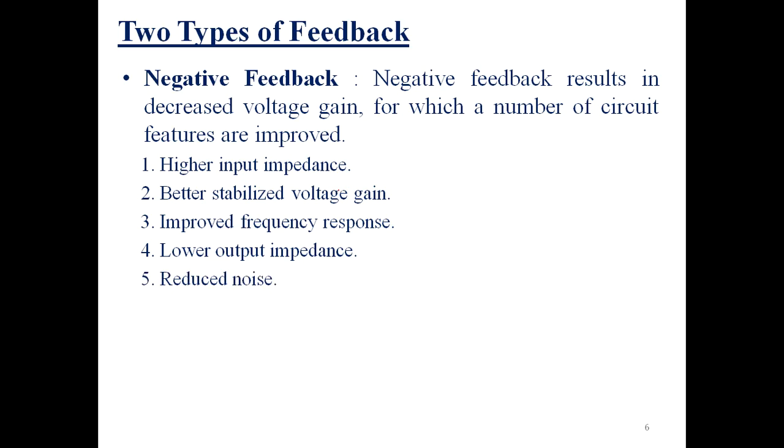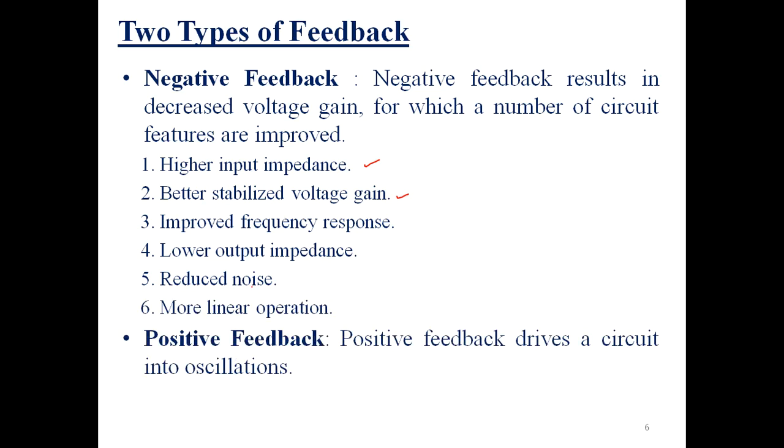What are the beneficial points of negative feedback? Higher input impedance, that's the most important point. Then better stabilized voltage gain, improved frequency response, lower output impedance, reduced noise, and further, more linear operation.